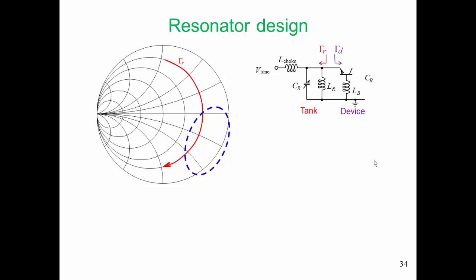And when we're at microwave frequencies, we really need to keep the resonator network as simple as possible if we're going to achieve all of our objectives. So we want the resonator network to be essentially a simple parallel LC circuit, and we're going to build on that and make it a little bit more complex. For example, we will replace the capacitance by a Varactor diode, and we will replace the inductance in the resonator network by a transmission line.